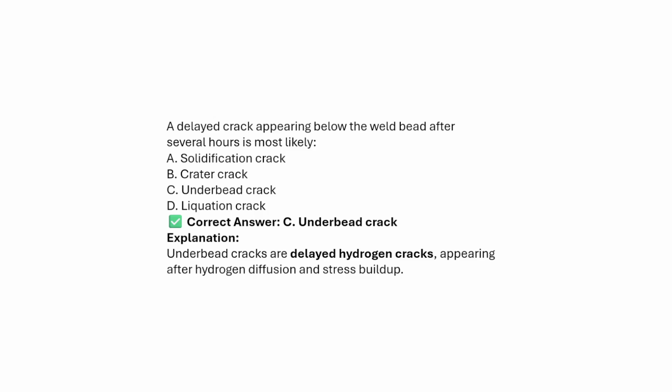A delayed cracking that appears below the weld bead after several hours is most likely which? Solidification crack? Here we have to see two things: it is below the weld bead, and it is delayed cracking. Delayed cracking is nothing but cold cracking or hydrogen embrittlement cracking. If the same cracking happens below the weld bead, it is called underbead cracking.